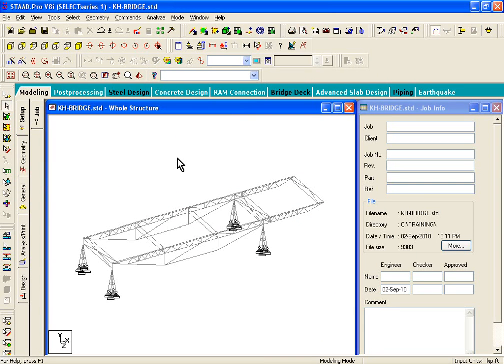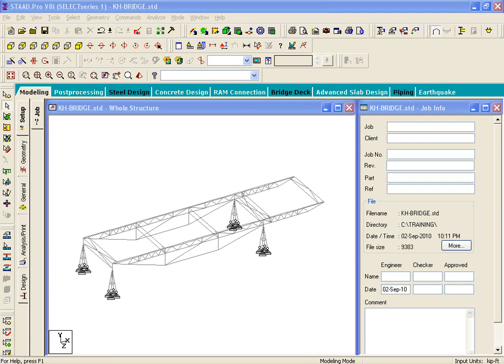Now we also have the physical beam definition, which is going to help you a lot in order to generate the loadings. The first load case is basically going to be L1 equals 8.8 feet, and L2 is going to be located at 1.1 feet. When I say L1 and L2, I'm referring to the instructions given in the AISC Steel Bridge Competition manual for 2011. Now let's create that load case.